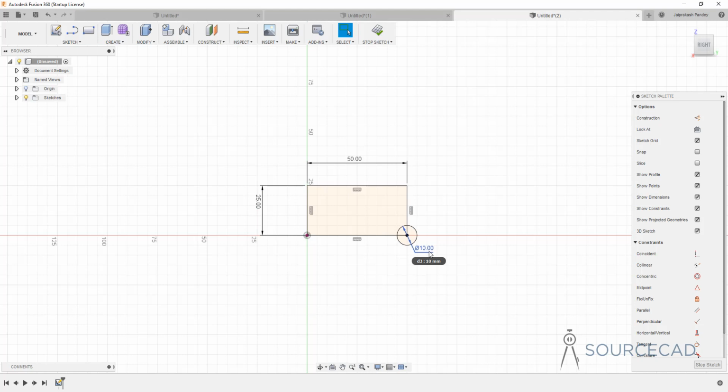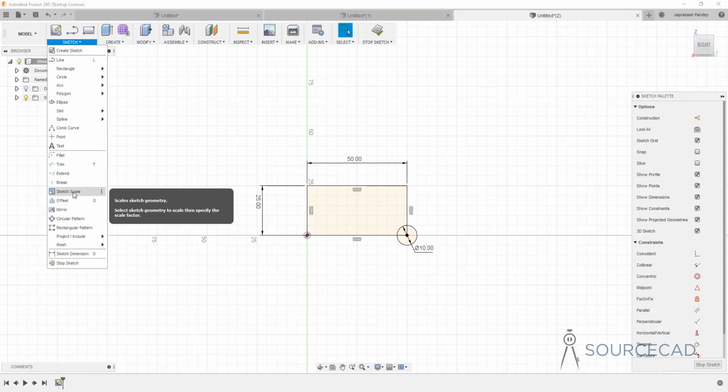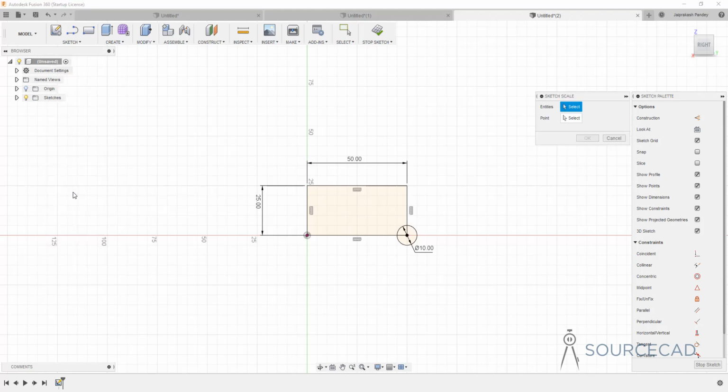So in order to ease this, I'm going to now use a sketch and sketch scale tool. So I'll select this, and now you need to select these entities that you want to change. So in this case, I'll just make a window to include everything here. Now 10 objects are selected, and they will be scaled up or down depending upon your selection. Now click on point and specify a base point. The base point will remain fixed. In this case, I'm going to select this as the base point because this is the point that we want to keep fixed. Now the current scale factor is 1.